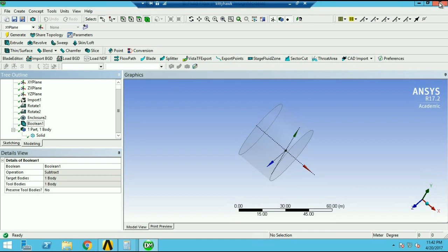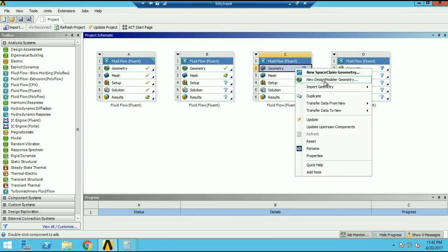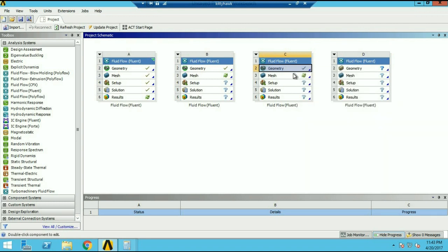So yeah, and then you basically just have to do that each time. One thing that does make it faster is if you save it in Design Modeler, and then you can just import the Design Modeler file instead of the Rhino model, so you don't have to do that initial 90-degree rotation every time. So if I did that 90-degree rotation and then exported that model in Design Modeler and saved it, like here I saved it as base 2, I can just load that, and then go back into Design Modeler and it's already there. You don't have to re-import, which takes like 30 seconds, and you don't have to do the rotation, which takes 30 seconds. So it saves you about a minute each time. So I would recommend doing that.